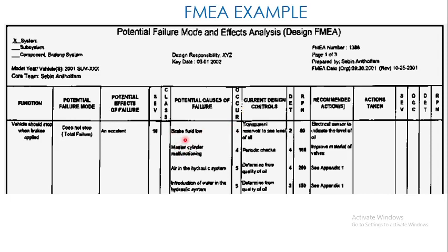Okay, so when the fluid is low, you apply the brake, the pressure is not being generated. Your master cylinder is malfunctioning. That means the seal of your master cylinder has leaked, or there is some sort of locking, or some component is broken, so it's malfunctioning.